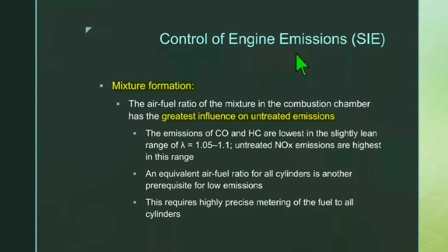Control of engine emissions (SI engine). Mixture formation. The air-fuel ratio of the mixture in the combustion chamber has the greatest influence on untreated emissions. The emissions of carbon monoxide and hydrocarbon are lowest in the slightly lean range of lambda equal to 1.05 to 1.1. Untreated NOx emissions are highest in the range. An equivalent air-fuel ratio for all cylinders is another prerequisite for low emissions. This requires highly precise measuring of the fuel to all cylinders.